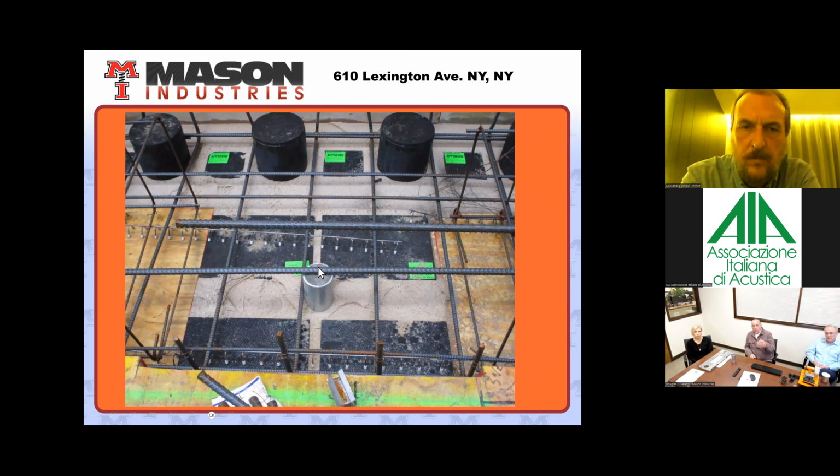In reality, it looks something like this. So you're seeing bearings that have been tested. That's those green stickers on each of the bearings. And this area is filled with sand, and that gets removed after the concrete is poured. These are pouring forms that get removed as well. These are the shear pins covered with an elastomeric membrane that's 50 millimeters thick so that it can handle the horizontal loads. And every one of these approved stickers means that each one of the bearings was tested to over 200% of the rated load.